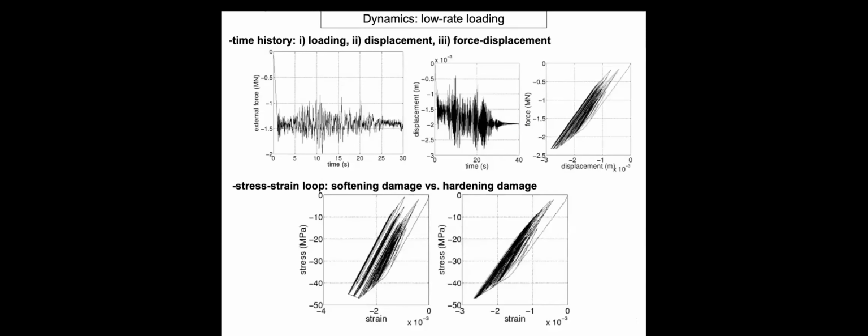That was also complemented with the hybrid stress formulation of our problem, so that you can have a very robust computation with linear hardening and softening. We were able to cover the typical area of the hysteresis loop, which means you have the same energy dissipation for each cycle, but with just linear hardening or softening. That means you can have a single iteration to get the right result, and you are able to get quite good results for this type of damping phenomena.